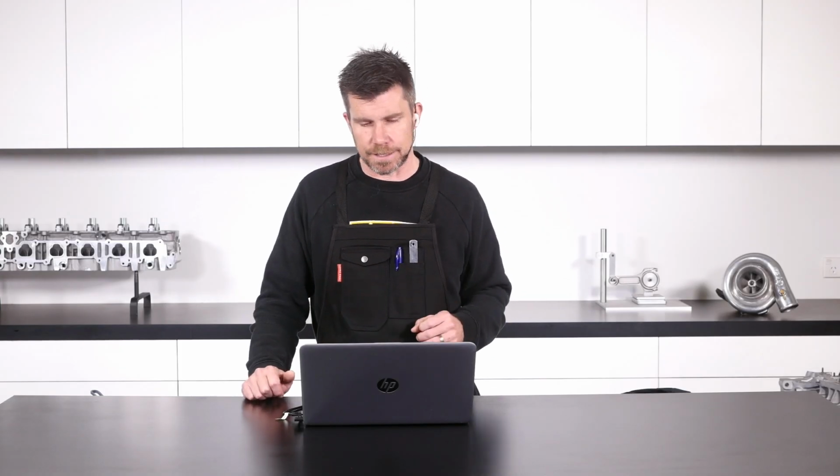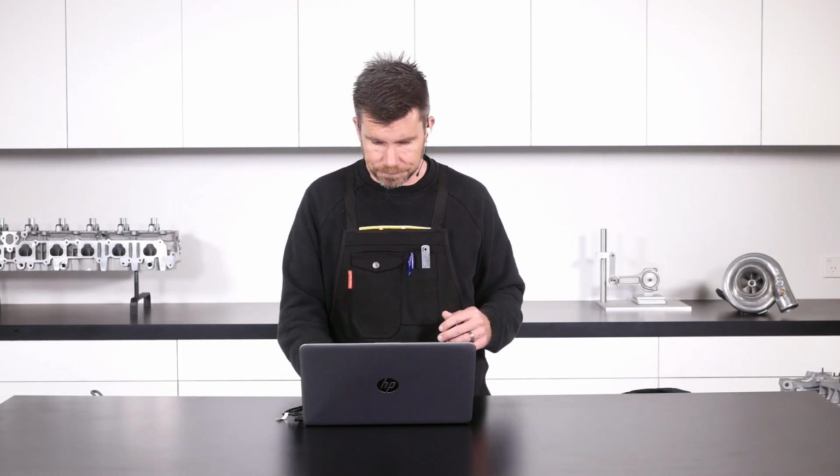The way I kind of dumb it down is the turbine wheel is kind of a coarse adjustment for getting the flow and response out of the turbocharger, and then the turbine housing is kind of a fine tuning. So you can't fix a very laggy turbocharger setup just by going to a tight exhaust housing. That's not going to be the solution. Both parts need to be considered in conjunction there.